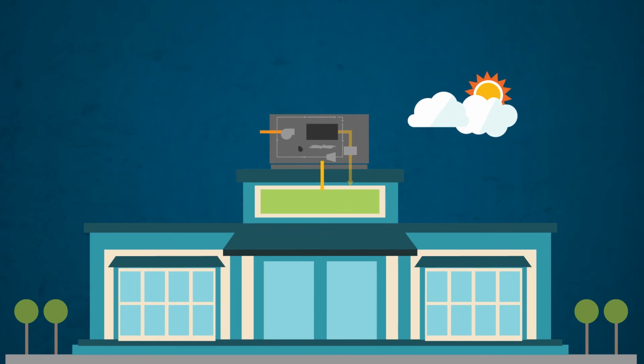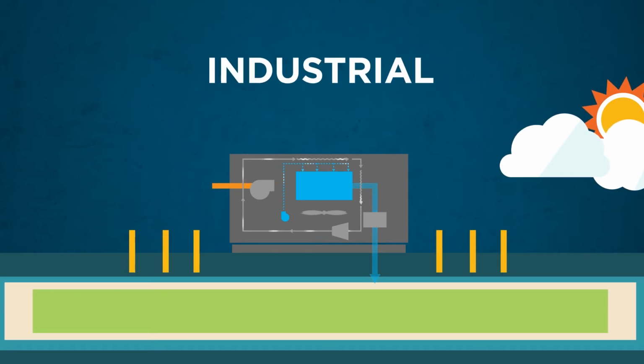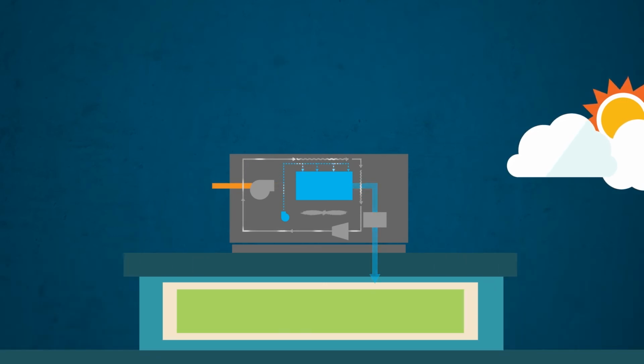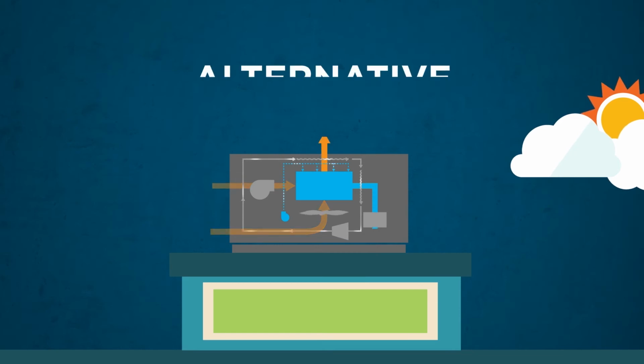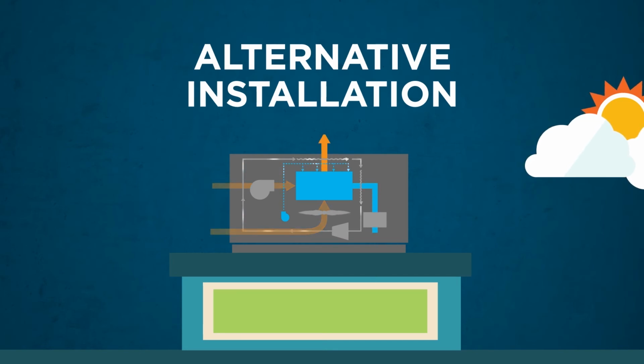The setup we described so far utilizes exhaust air to save energy in ventilation, cooling, and heating modes. However, certain buildings are not suitable for this approach. Restaurant kitchens have large heat exhaust loads, making exhaust air unfavorable for evaporative cooling. Industrial buildings that use fume hoods to exhaust building air do not have a centralized exhaust point. To address these limitations, the EPX is designed to provide an alternative installation option that uses outdoor air for the second airstream. Although this setup does not allow heat recovery from the exhaust airstream, the unit still provides efficient cooling by utilizing the evaporative cooling strategies described earlier.